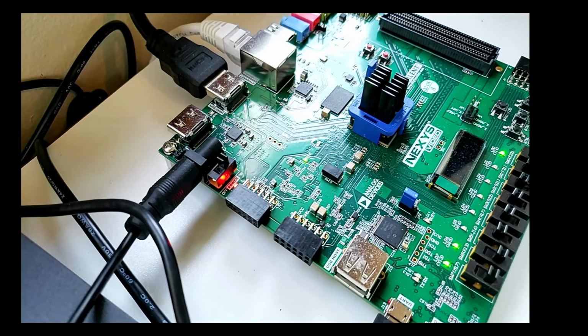I can't afford to fabricate chips. We can't afford to do that for this class, right? If you take the VLSI sequence, you get a little bit of an experience in doing that potentially. But for this class, we want to test 500 designs quickly. We don't want to build a design, wait for 6 weeks, get our chip back, and test that. So FPGAs are wonderful for that purpose.